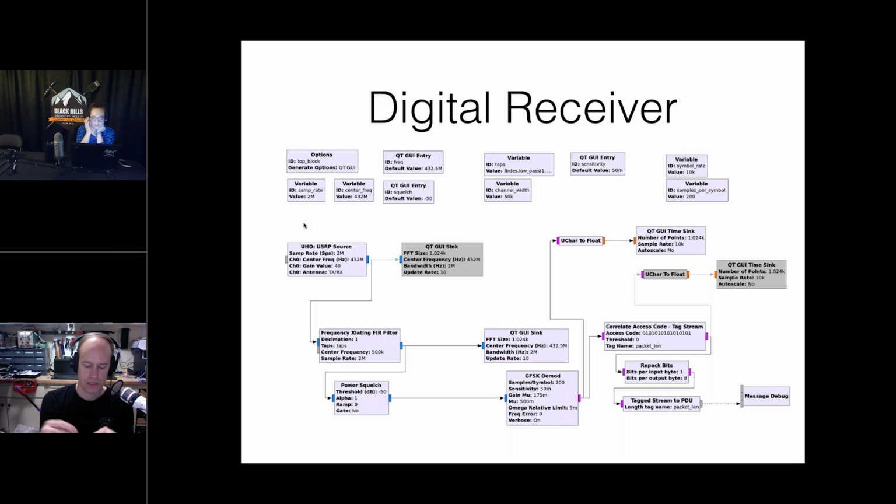So just as a practical rule of thumb, if you're working with the HackRF and you're working at max power, you can jam somebody trying to get into their car from maybe 20 feet away. That's going to vary based on the conditions, but that's the kind of rule of thumb. You're not going to jam somebody across a football field with something like this. For that, you're going to need a directional antenna and or a power amplifier.